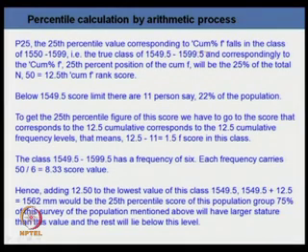If we add it, 1549.5 plus 12.5 equals 1562 millimeter, which would be the 25th percentile score of this population group, where 75% of the surveyed population mentioned in the first slide will be of larger stature than this value and the rest will be below this value. Like this, all the percentile figures we can calculate accordingly.